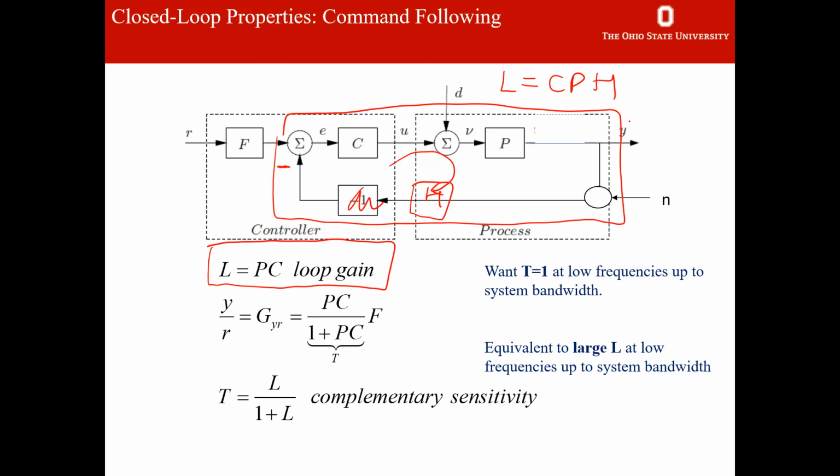And if I do some block diagram algebra, Y divided by R. Now at this point, I have F times R as my input. This is a feedback loop. Remember your block diagram algebra, and you are going to refresh that as part of this new homework set. From the previous course, we multiply everything in the forward path from the input F times R to the output Y. So Y divided by F times R is going to be in the numerator.